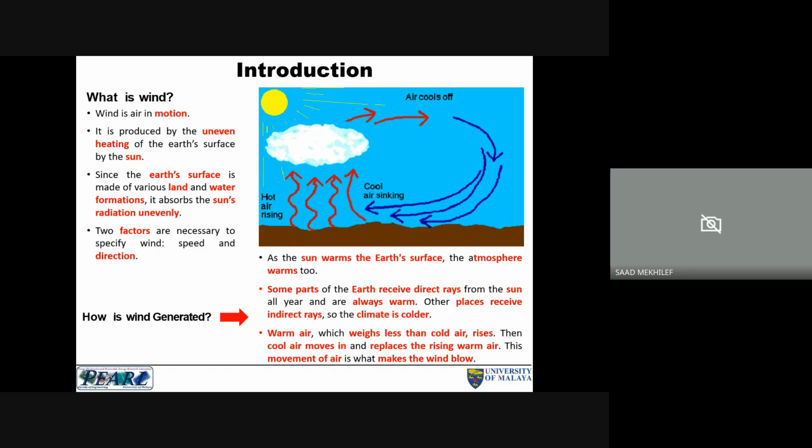There are others, for example the clearance and the dust, which affect it. But the two main ones are irradiance and temperature. And then we have seen how the power curve changes with respect to changes in irradiance and temperature. The same for wind: there are two main factors, which are wind speed and wind direction.